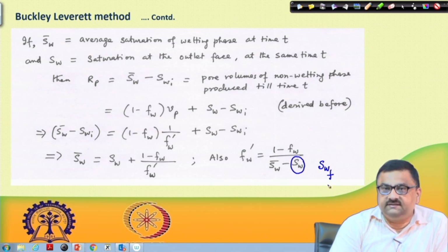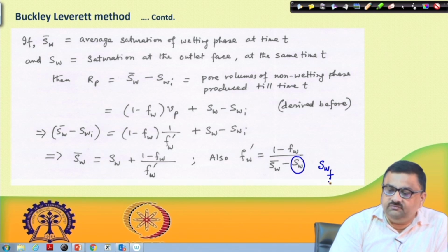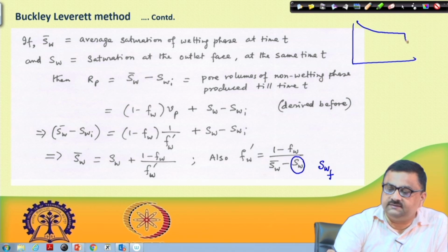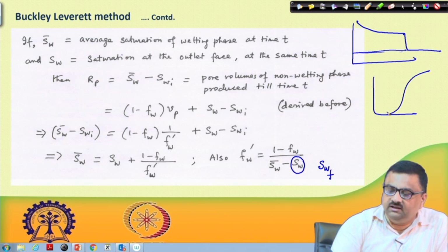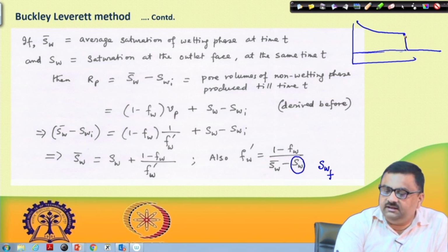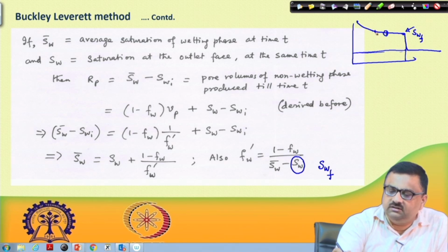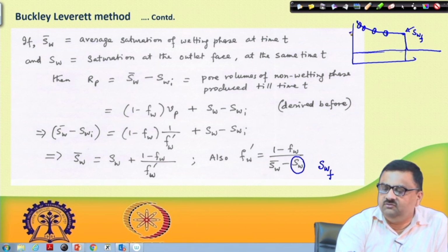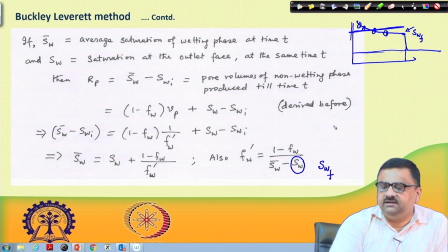So, the Buckley-Leverett front has reached x equal to L, and you can see this saturation profile takes a shape like this. This is SWI, but here this is higher than SW, because of the way the FW curve is. Had the FW curve been in some other form, probably the tangents and all would be different. I will show that in a moment, don't bother about this part. When the saturation here breaks through at x equal to L, we call this SWF, to differentiate it from any other saturation value. So, SW would be any individual saturation value, and SW bar would be simply the average of these saturations. That is something we are heading to.